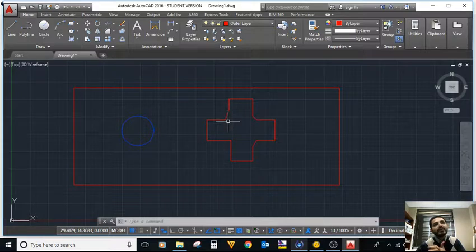In so many cases, you would use a certain scale to draw your drawing, and then all of a sudden you are asked to put this in a new border scale, or the scale is being changed. Maybe at your company you're using 1 to 100 inches. 1 inch in the drawing is equal to 100 inches in real life. Maybe now you want to shift that scale. If you don't have that option, you need to redraw the entire drawing again, and that's painful. So in order to avoid that, there is an option to scale the entire picture, either smaller, or in or out.